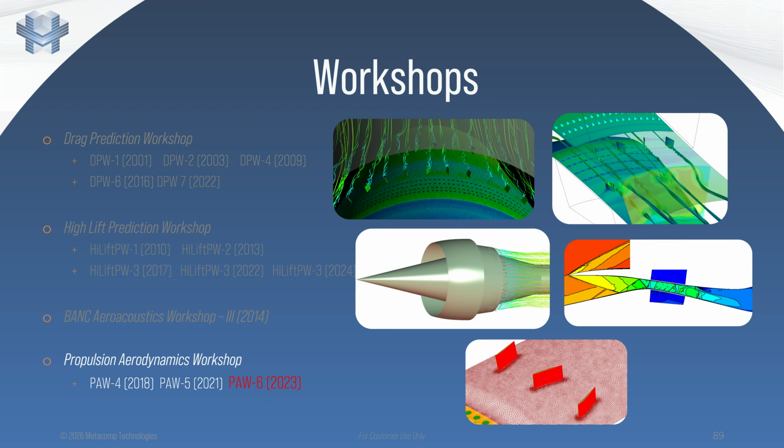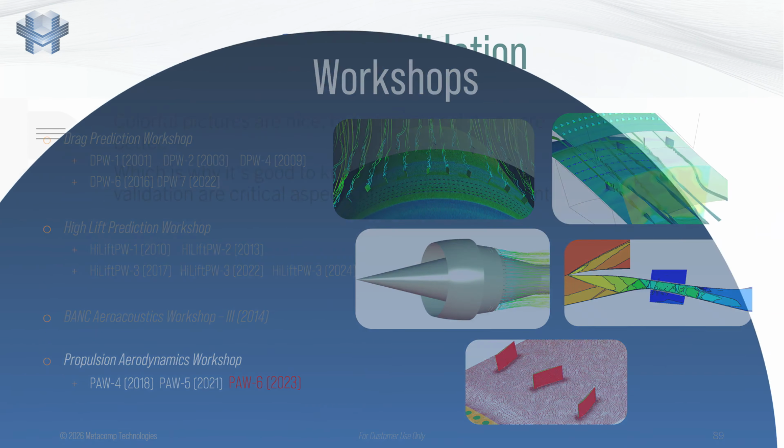At the 6th Propulsion Aerodynamics Workshop, CFD++ was able to capture a mixed compression intake with an internal shock structure, incorporating porous bleed regions and vortex generators. The mesh for this case was generated using Metacomp's own general-purpose mesh generation software, MIME.